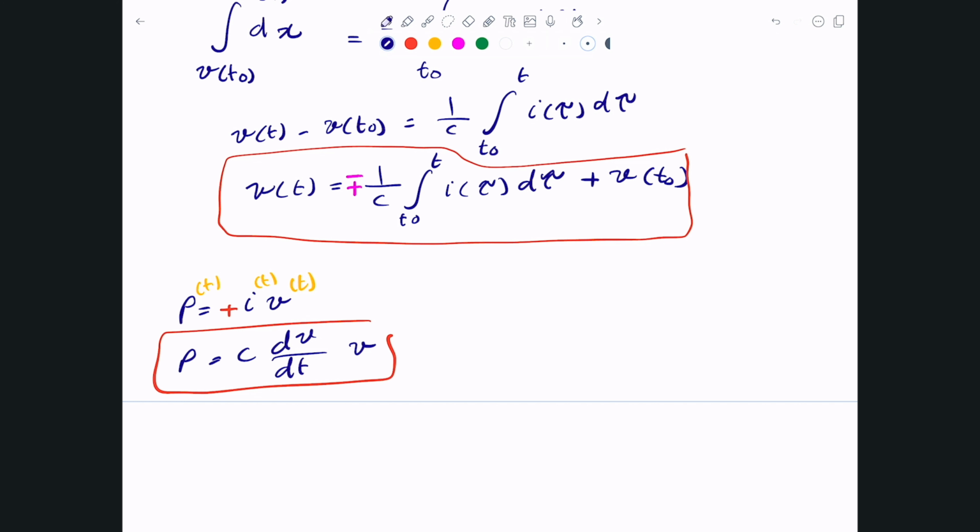All right, so we can also compute the power as P equals simply, we keep the I, and we replace the V with 1 divided by C times the integral from t0 all the way to t of i of tau d tau, plus V of t0. You can just compute it this way. And again, passive sign convention applies in here if you wanted to.